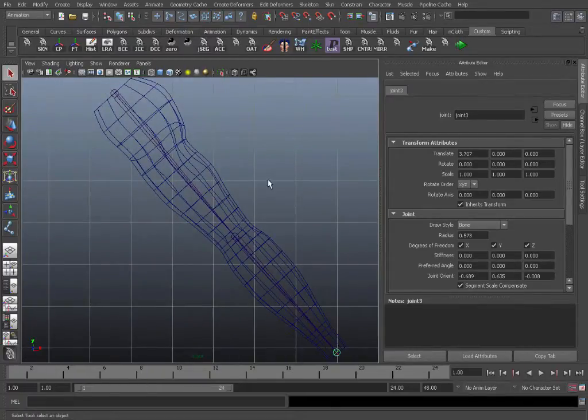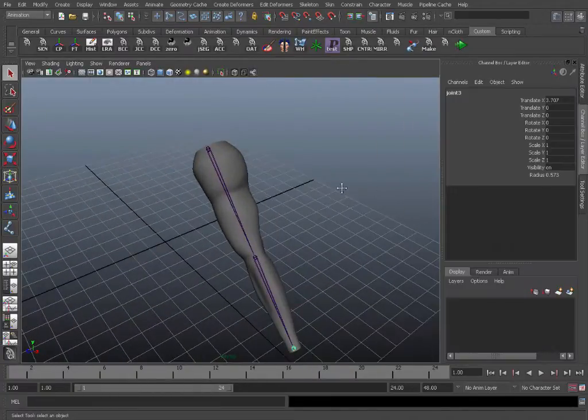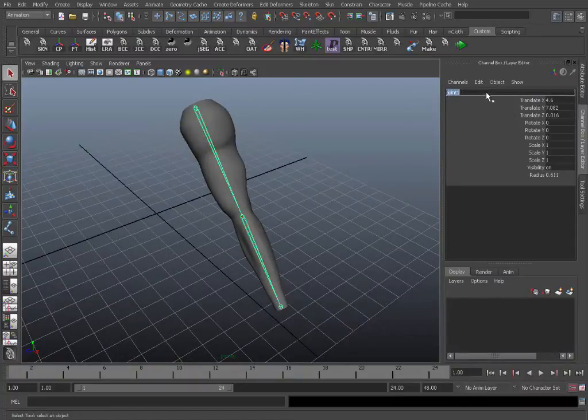Right, so next we'll quickly rename these joints. Go into perspective, make sure X-ray joints is on so you can see it. We'll use a prefix of SK. Change that to SK_L shoulder, copy the name, paste, rename that to forearm, and finally we won't be skinning to this bone, as in this example the arm doesn't have a hand, so we'll change this to end_L wrist.